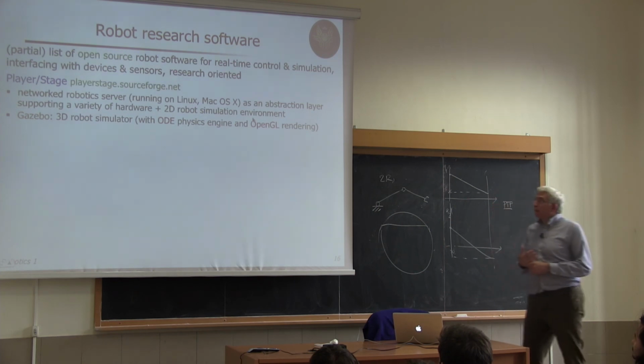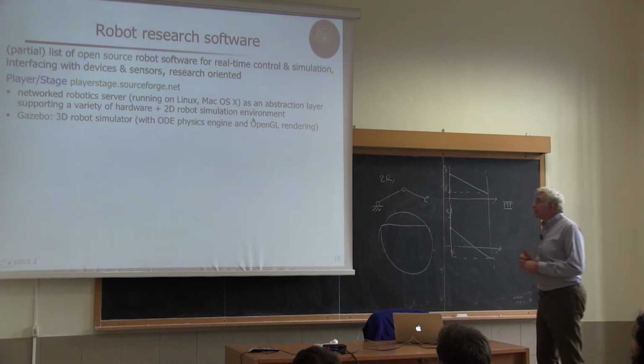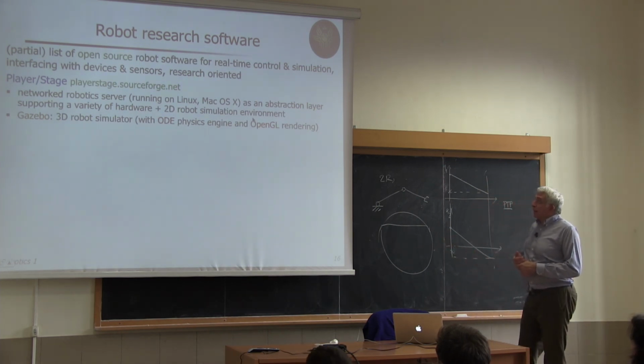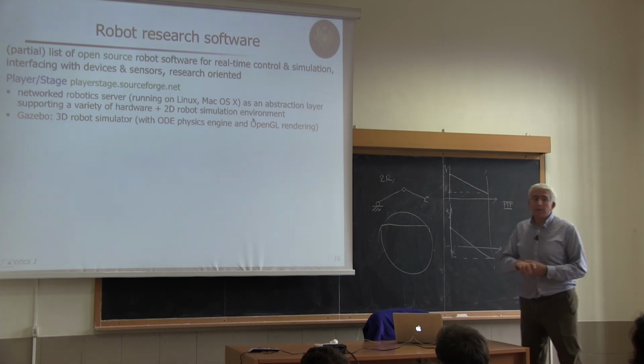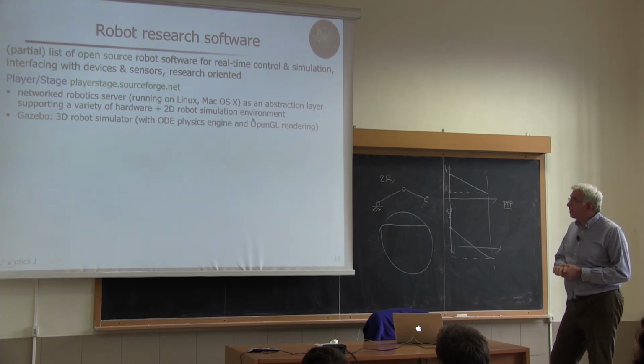One project was Player/Stage, so this is a robot server for network robotics. It works under Linux or Mac OS systems. And it can be interfaced to a large variety of hardware, and the Stage version provides also a nice two-dimensional simulation environment.